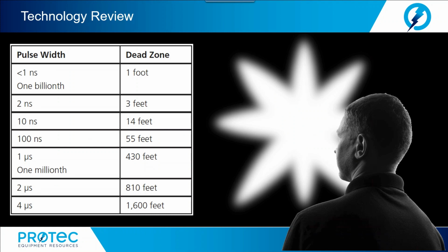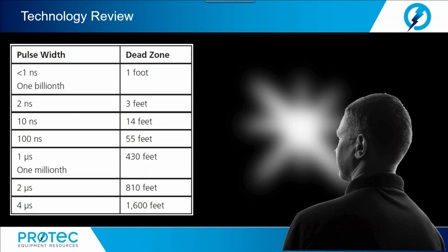So why don't we just send the most powerful pulse at all times? The width of the transmitted pulse will affect the TDR's ability to identify reflections. It's a bit like walking in from the dark and turning on a bright light. The power of the light overpowers our receivers, our eyes, and blinds us for a minute. Our eyes adjust by reducing the amount of light that enters our receivers. Now, the TDR's receivers don't do this, so lower powered pulses for close-in events have to be set.